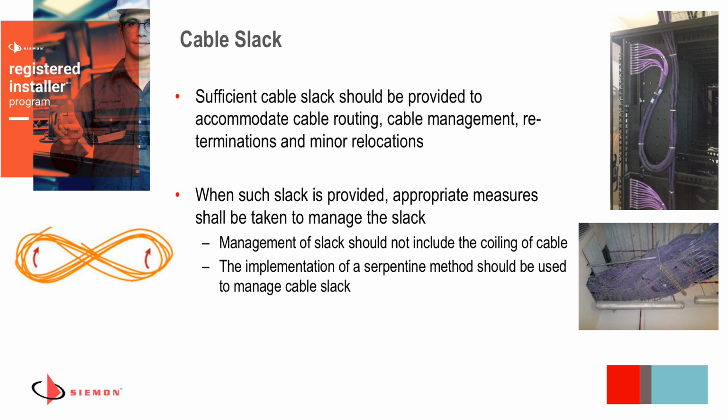And we mentioned cable slack earlier, and it's important that slack is available and left at the end of the cable pulls to properly route the cable to its final termination point, to address proper cable management, and especially as there sometimes can be re-terminations and relocations along the way at the last minute. You want to make sure you don't have to re-pull an entire additional cable. So it's important to give a little bit of slack at both ends, and where you have it, you want to make sure you manage that slack.